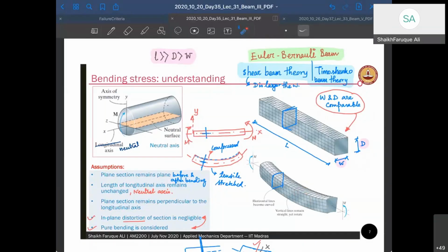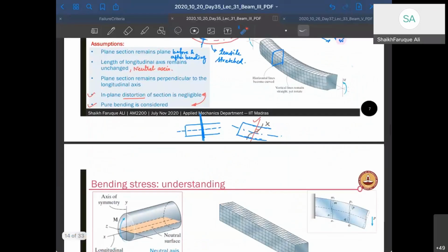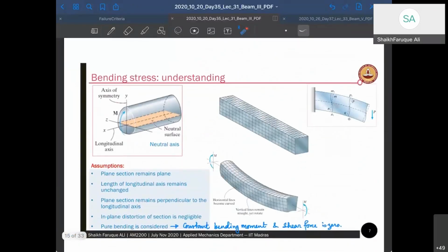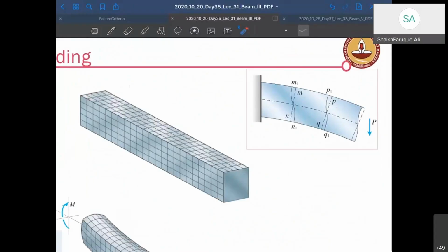Okay. So what happens if you take an axis, and you take a line perpendicular to it? That line will remain perpendicular to the neutral axis before and after deformation. So that's one of the very important assumptions for small deformation. Here, if you see this picture, this is a deformed neutral axis. My MN line was perpendicular before deformation, and will remain perpendicular even after deformation, but it will get inclined a little bit. To remain perpendicular, it has to incline, right?